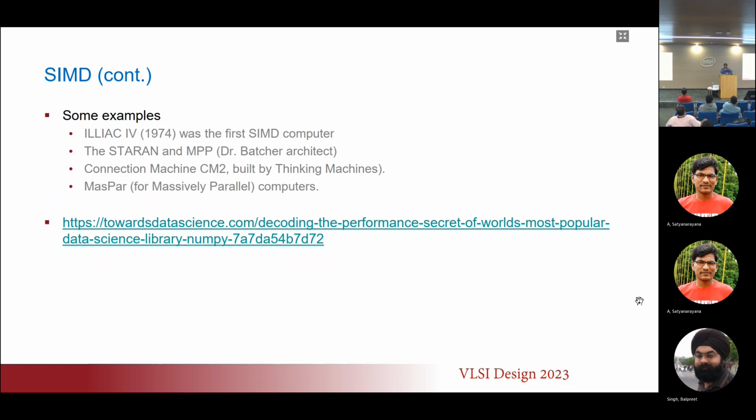Now, remember, if my filter size was 3 by 3, then with one filter, I'm packing 9 pieces of data. But my register can store 64 pieces of data. So what would be the best way to reorganize my computation? So I can do more than one filter at a time. I can put the first filter here, the second filter there, the third filter there, until I have filled up the entire register, the 64 pieces of data.